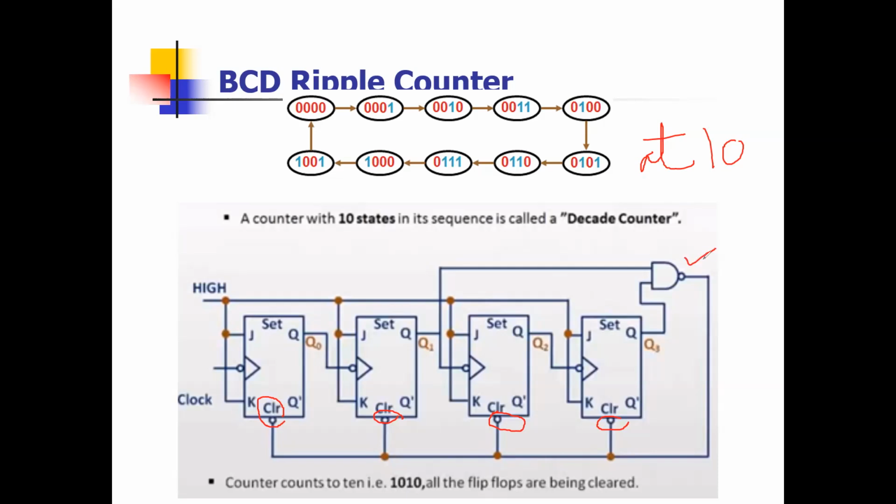So you need to check whether you have a bubble for the reset or you have it without a bubble. According to that, you need to use that particular gate. Maybe you can use XOR, maybe you use another gate. So it's your choice which gate you are going to use. But in the slides, I show you when you have to use an AND gate and when you have to use a NAND gate. Clear? Why didn't he take the output for the other flip-flop?